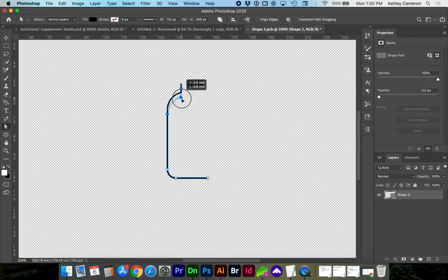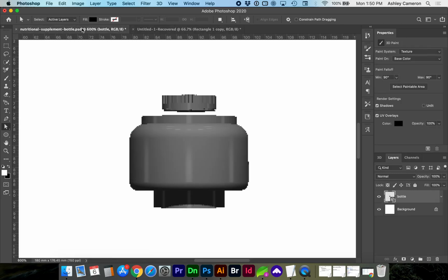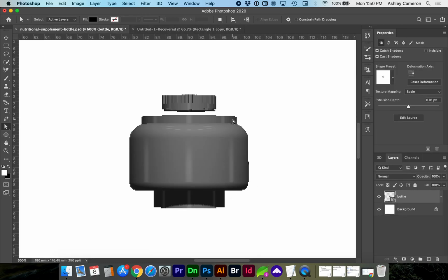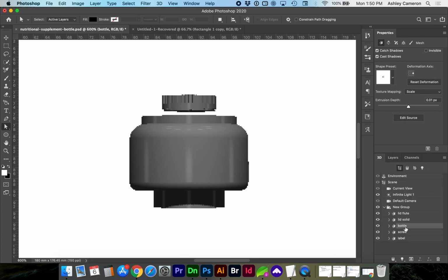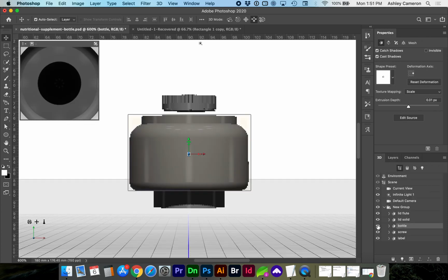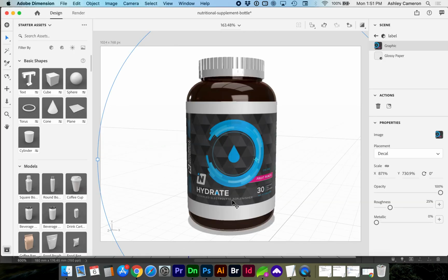And you can also make it wider or narrower. So let's say we're going to make this really wide so we can see a difference. It's shorter and wider. We're going to save, Command S, this shape, close it, and you can see if we go back that it's directly modified our 3D object. So now you can get a better idea of how you can edit from either the vector parts, or revise the dimensions in Photoshop, or make your adjustments in Adobe Dimension.